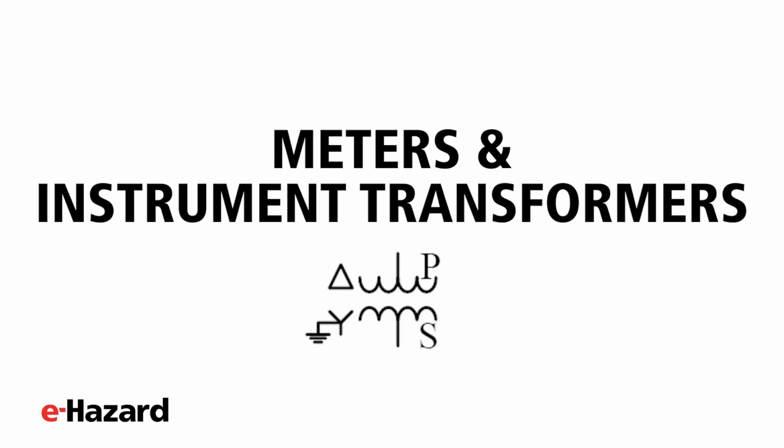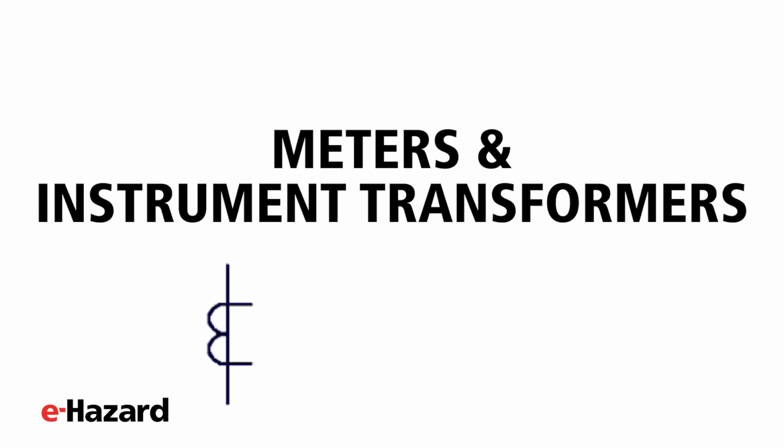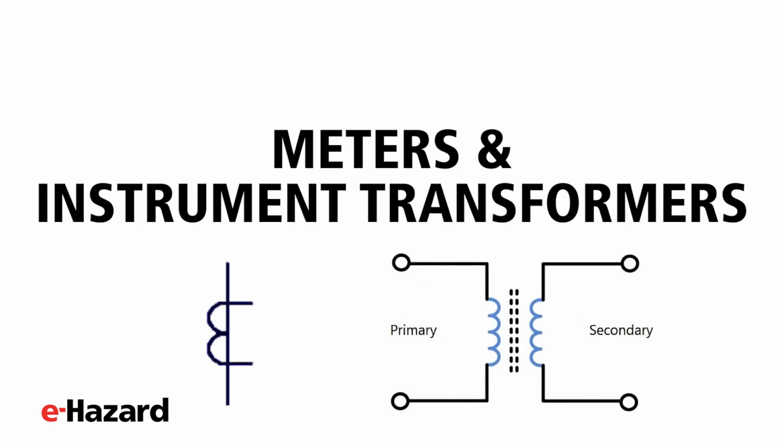Meters and instrument transformers. Circles with letters inside represent metering devices. A is an ammeter, V is a voltmeter, W is a wattmeter, and kWh indicates an energy meter. You'll also see CTs, current transformers, and PTs, potential transformers, nearby. These step down current or voltage to a safe level for metering.